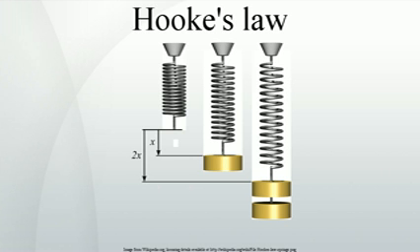In order to capture this complexity, the relevant state of the medium around a point must be represented by two second-order tensors, the strain tensor, in lieu of the displacement, and the stress tensor, replacing the restoring force. The analogue of Hooke's spring law for continuous media is then the stress equals the stiffness tensor applied to the strain, where the stiffness is a fourth-order tensor, that is, a linear map between second-order tensors, usually called the stiffness tensor or elasticity tensor. One may also write it with a compliance tensor, which represents the inverse of said linear map. In a Cartesian coordinate system, the stress and strain tensors can be represented by 3x3 matrices.